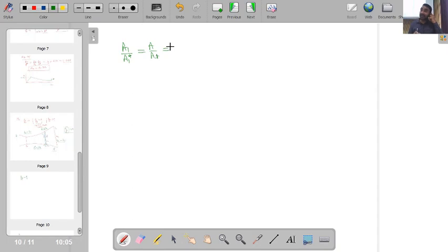Because A1 star is equal to A t, and as the shock wave is very thin, just upstream of the shock wave is nothing but the location of the shock wave. So it means A1 is equal to A, because A is the location at which the shock wave is forming. So this will be equal to A by A t, which is equal to 2.